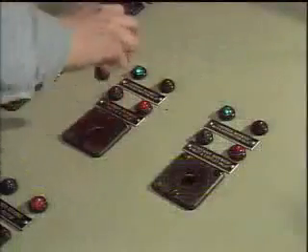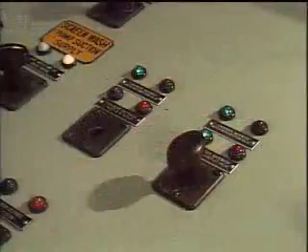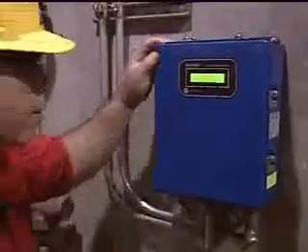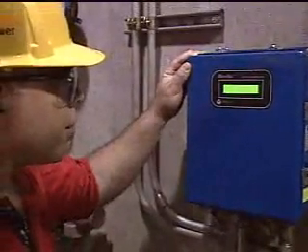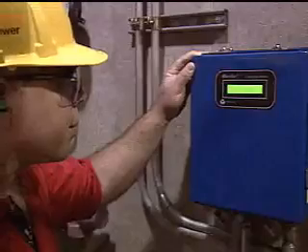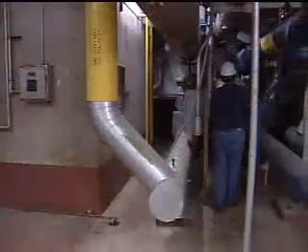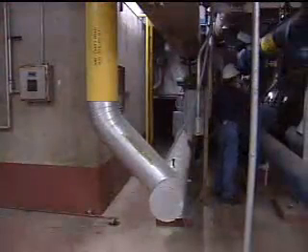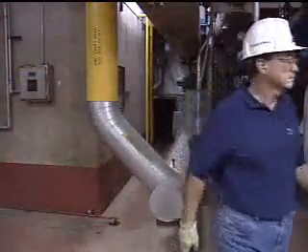Tube cleaning is a fairly routine operation, but in some cases it may require half of the condenser to be shut down for the cleaning process. If an air leak is suspected as the cause of the low vacuum condition, you should check the airflow monitors or air leak detectors in the air removal system. If the airflow reading is higher than normal, the condenser and every system connected to it must be carefully inspected so that the source of the leak can be found and corrected.